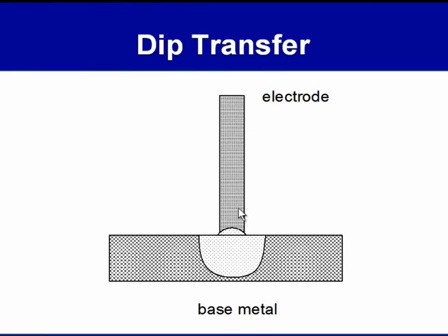When the welding current goes above the range of the spray mode of metal transfer, rotational transfer is observed, and when it takes place, a lot of spattering occurs, which causes a reduction in deposition efficiency and the falling of the molten metal here and there. So, it is always required that such a rotational mode of metal transfer does not take place during welding.